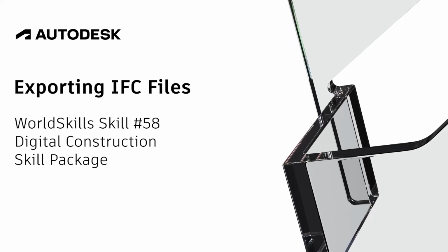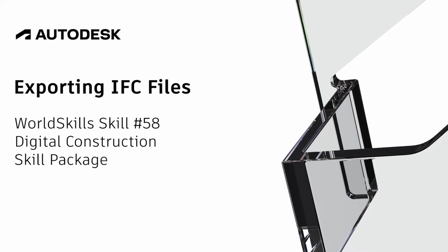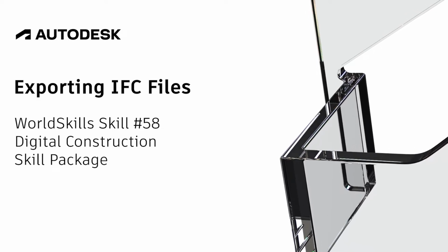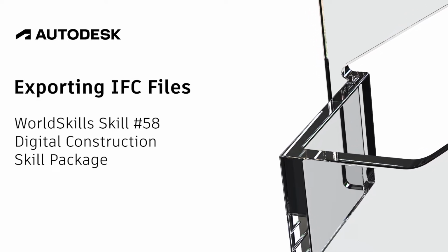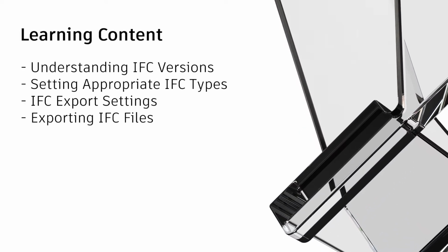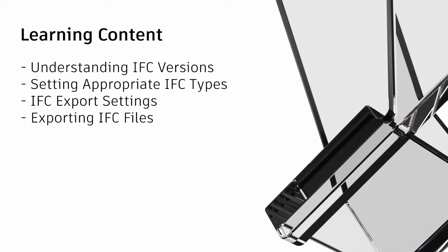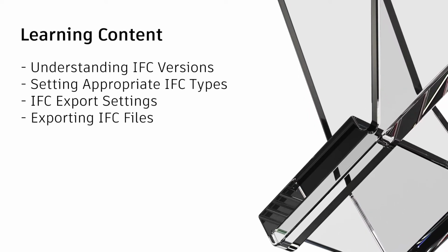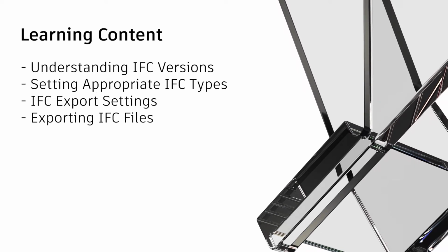This video will look at correct export and understanding of the IFC file, or Industry Foundation Class, inside of Autodesk Revit. The learning content will be understanding IFC versions, setting appropriate IFC types, your IFC export settings, and how to export IFC files.